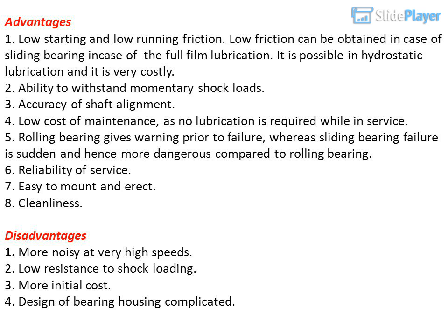5. Rolling bearing gives warning prior to failure, whereas sliding bearing failure is sudden and hence more dangerous compared to rolling bearing. 6. Reliability of service. 7. Easy to mount and erect. 8. Cleanliness. Disadvantages: 1. More noisy at very high speeds. 2. Low resistance to shock loading. 3. More initial cost. 4. Design of bearing housing complicated.